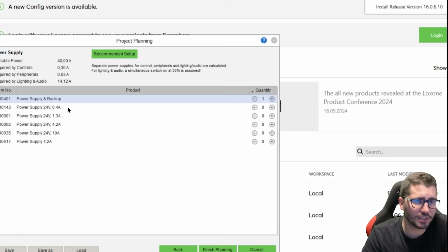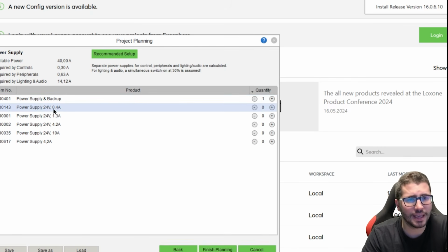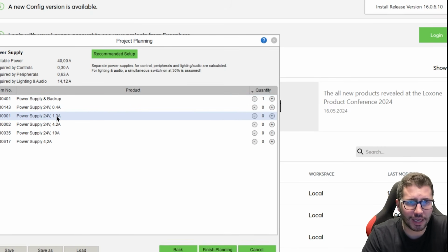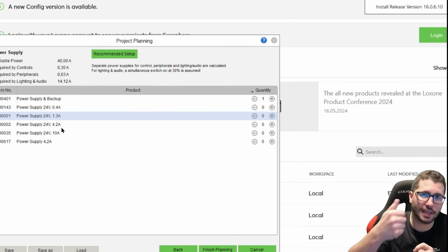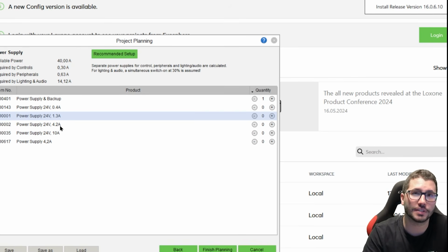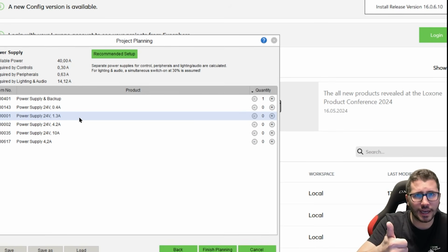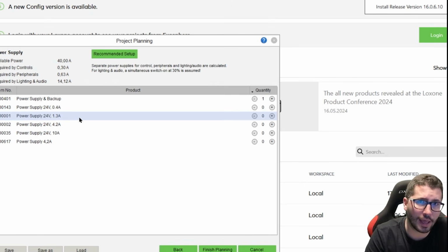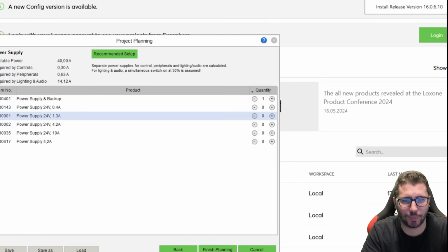If you, for any reason, do not do it, then I would use a dedicated small power supply for just the miniserver and its extensions, another one for the sensors, and another one for all the stuff, the actuators, the light, the LED strips, and so on. Because then in any case, if on the sensor side there is a short circuit, the miniserver is still working and you can control everything inside of the app.